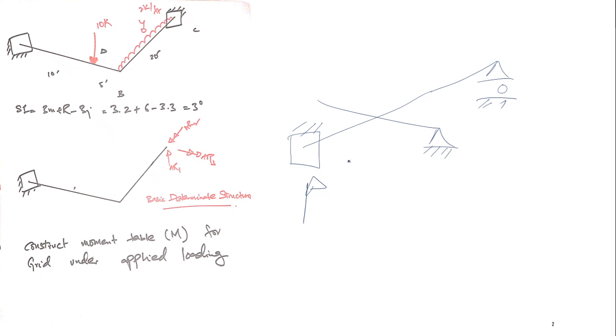Then vertical, the moment in x, the moment in z. Here only vertical, here only vertical, here no reaction. So the grid should be recalled. Okay, I have made it determinate by exposing 3 reactions. I have just omitted this support and 3 reactions are exposed now. So these are my redundant actions.